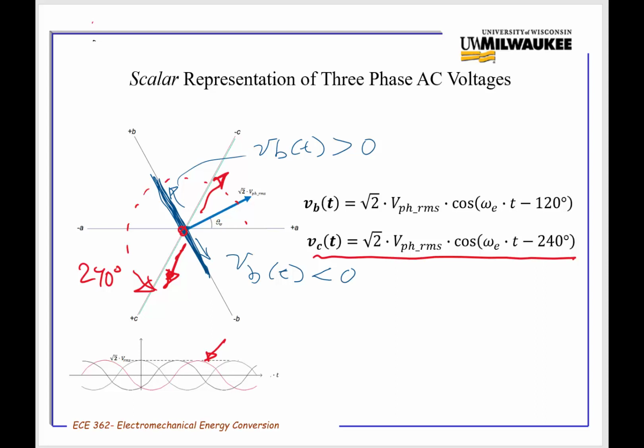And we could say, okay, let's go back and look at that 90-degree point right here. Look at all three of these voltages. They're happening at the same time, they're hitting 90 degrees. So we know that VA is at 0. We know that VB is at 0.866 times the peak voltage. VC at theta E equals 90 degrees.